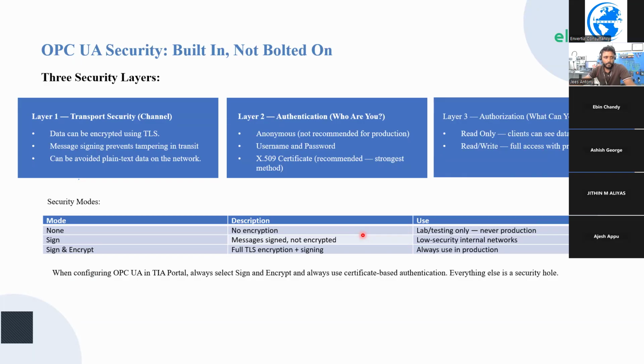And with the security principle broken, anybody from the hacker world can access and control your device if you are using Modbus TCP. If you have not protected that Modbus TCP network, you cannot protect the Modbus TCP communication at the device level. But with OPC UA, industry-standard security protocols like transport layer security and sign-based access can be very easily implemented. You can see that in the transport security division,